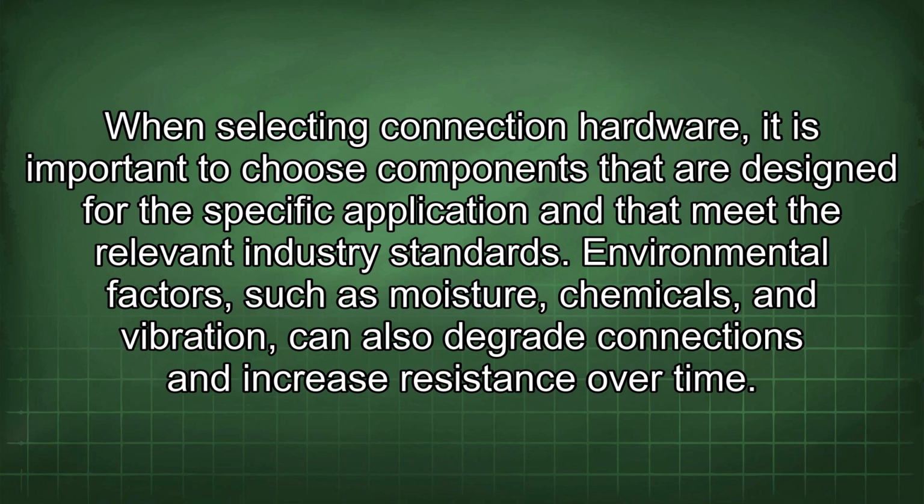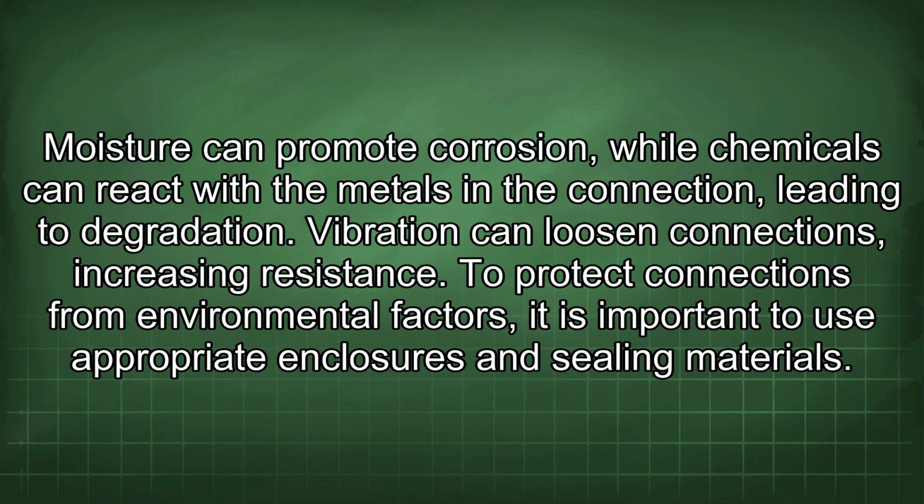the relevant industry standards. Environmental factors such as moisture, chemicals, and vibration can also degrade connections and increase resistance over time. Moisture can promote corrosion, while chemicals can react with the metals in the connection, leading to degradation. Vibration can loosen connections, increasing resistance.